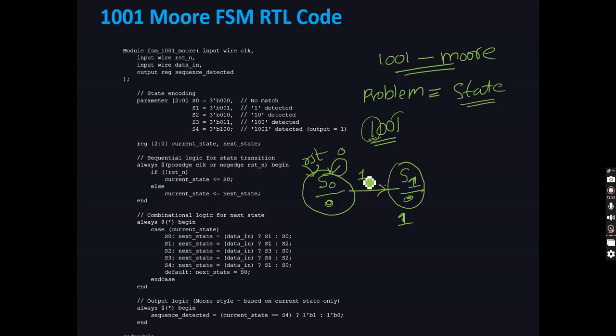If we do the reset, I am giving now 1. Since it detects 1, it goes to the next state, which is able to detect 1. Again I am giving 1 0, so we have the 1 0 state here. I am taking it as another state with output 0. Why am I taking output 0? Since it is detecting only two bits, again there are more states like 0 1. That's why we are making the output 0 only.